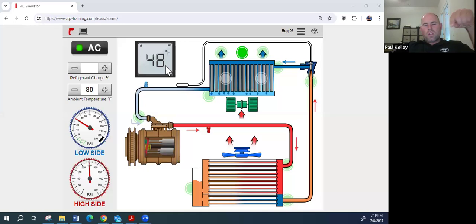Basically, your notes are what the FTS uses to defend the lemon law thing. So if you wrote, I went out to the parking lot, I checked this car with this VIN number and it blew this temperature, that's winning the case right there. But just to say NPF, that's losing the case right there. Make sense? Now I understand sometimes it's hard to get paid to do that type of stuff, but if you're going to take this job seriously and you want to be the master of your craft, you're going to really have to put some extra time in.